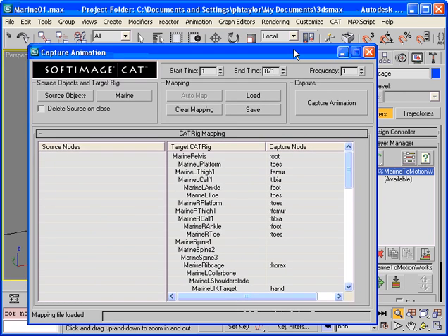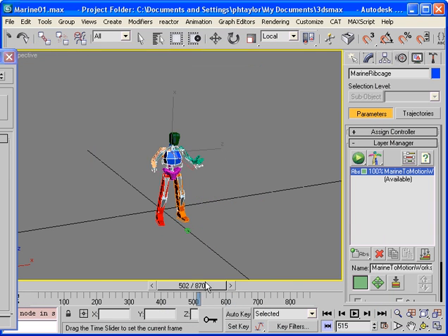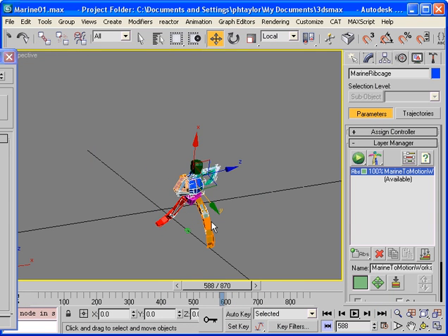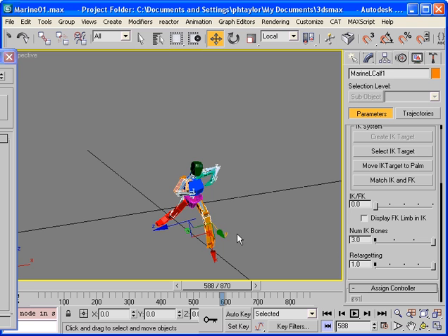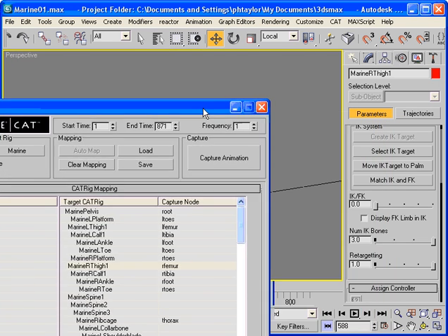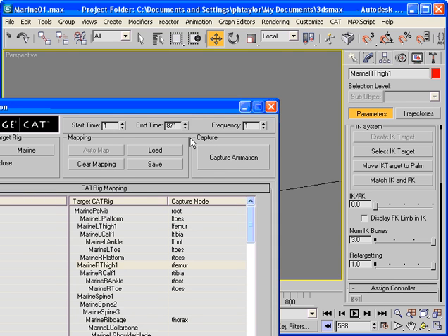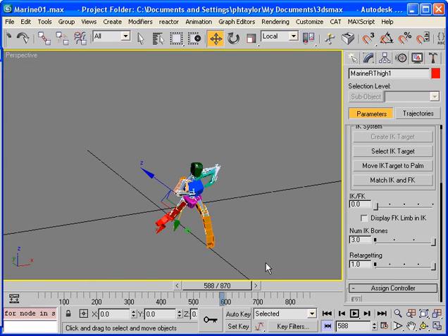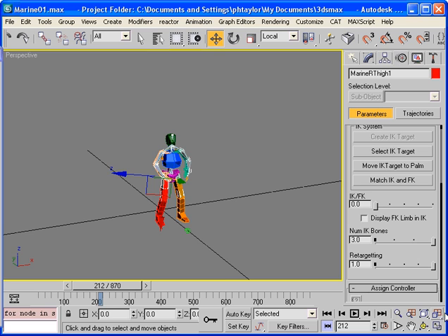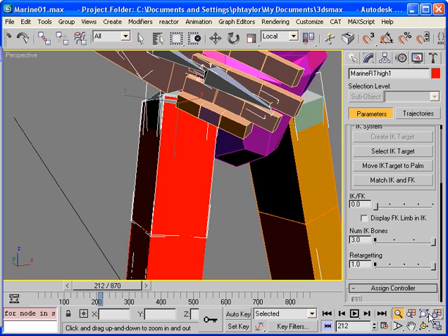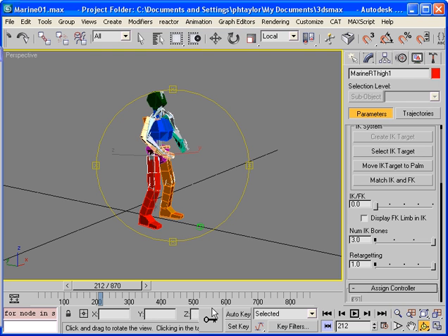So now we're going to capture this motion onto our character as keyframes. Right now, all the capturing process is purely procedural. So let's just turn retargeting back on, because the mapping file doesn't store the retargeting values, as retargeting is a shot-by-shot basis, and it's simply not stored with the mapping file. So here we have the motion as we'd like it.